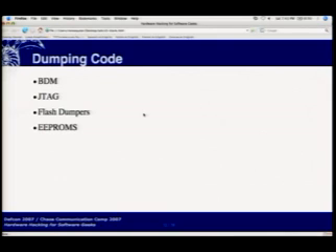Some BDM systems also let you do things like clock stepping to slow down the process and run, inspecting each register as each clock cycle passes, modifying registers, modifying memory locations. These actually have a BDM port on the back. As you see, I put a pin header on it. It's actually a one-wire bus that allows you to debug the chip.